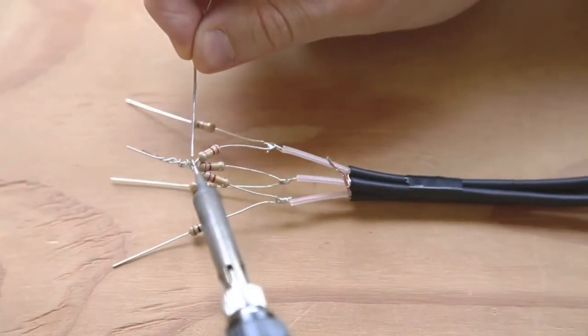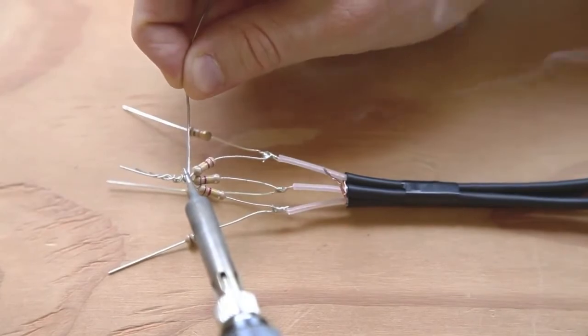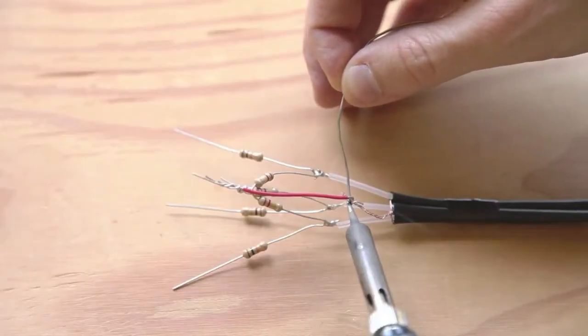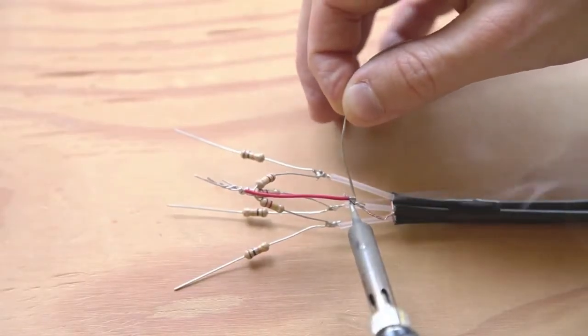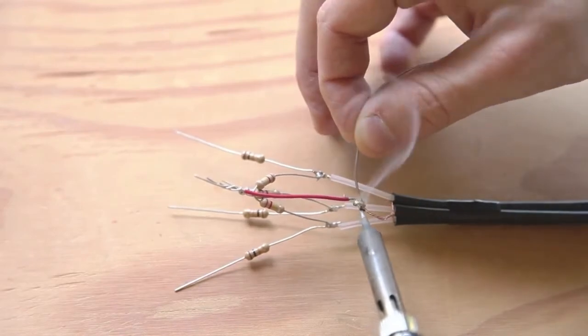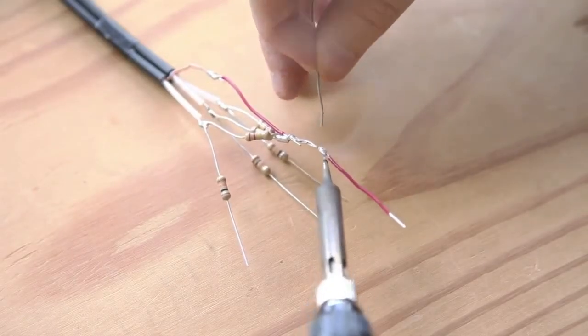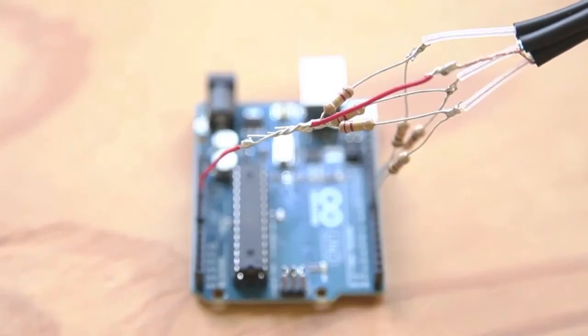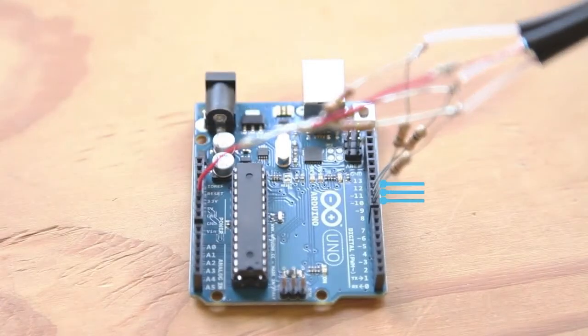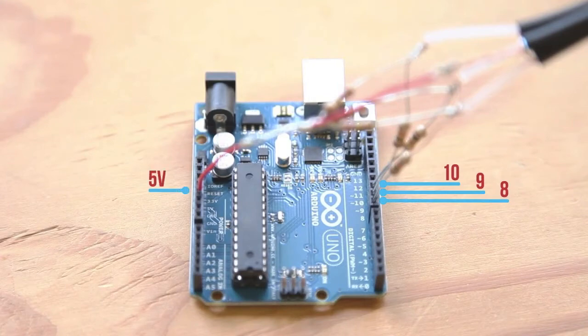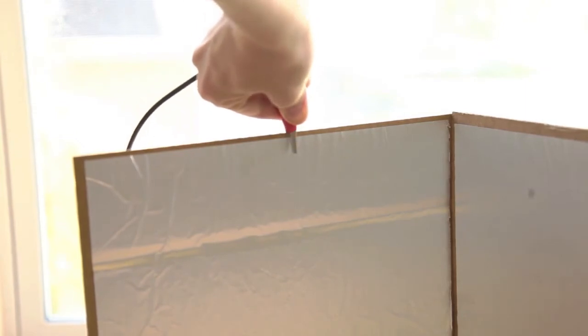Twist and then solder the 3 220K resistors together, then solder a piece of jumper wire from the shield wire to these resistors. Then add a second jumper wire from this junction. The wires are now ready to connect to the Arduino. Connect the 3 10K resistors to pins 8, 9, and 10. Connect the jumper wire to the 5-volt pin on the Arduino. Attach each of the alligator clips to a foil plate.